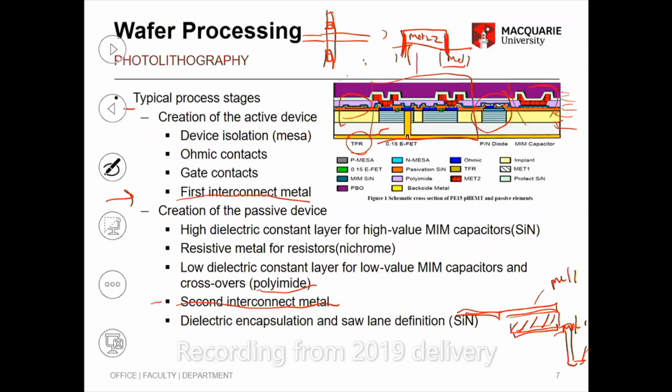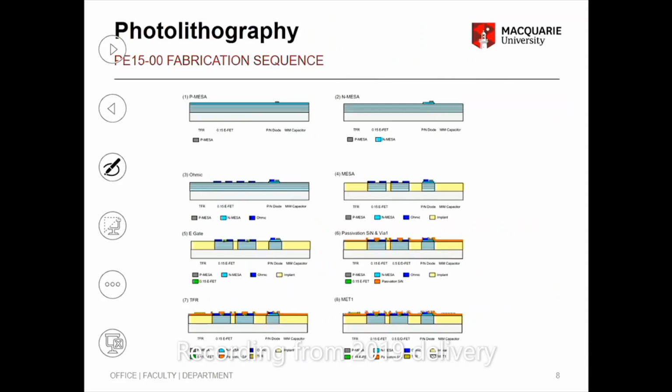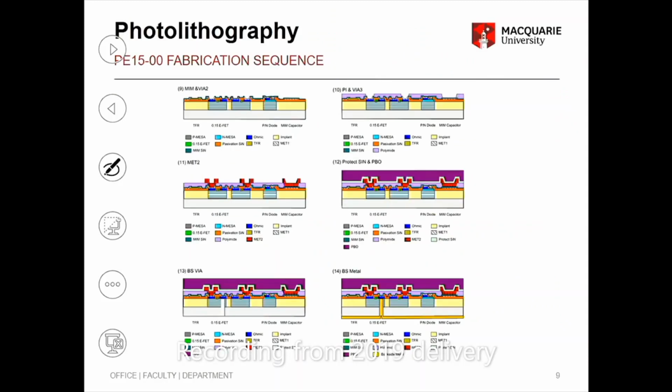That layout manual will have all these descriptions. There's a process manual and a layout manual. The process manual explains all this. The layout manual tells you the rules around each of the devices. For example, it will say a capacitor can't go below this width and length. Metal to metal spacing can't be less than 5 micrometers. A metal one strip has to be at least 5 micrometers wide.